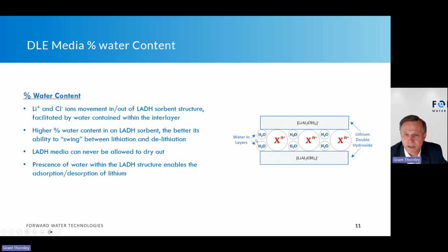The number could be anywhere from 1.5 to 4 water molecules attached to the inner layer, which we refer to as hydration. The more water that you have, we found that the better the swing, meaning the easier the lithium and chloride come in and out of the medium.